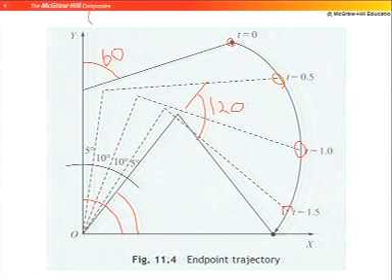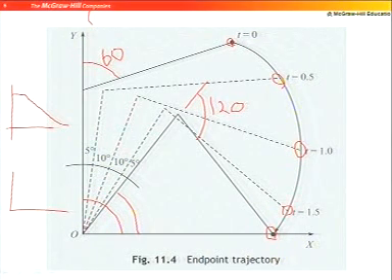So, in end effector space it has moved like this, even though if I plot your theta 1 movement, it was curvy, then a straight line, and then again curvy. Theta 2 has exactly the same curve, but with different values, but in xy motion what is shown is the final motion.